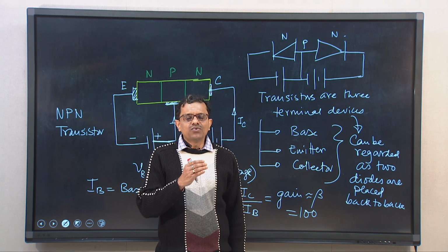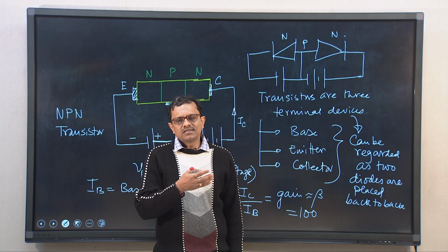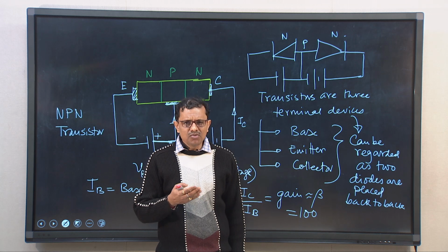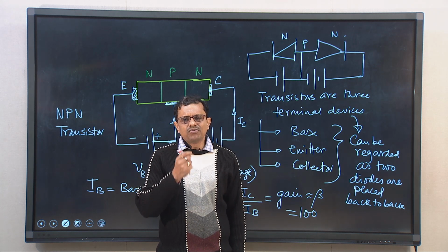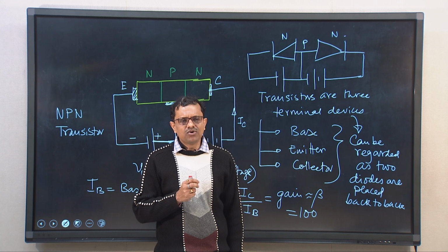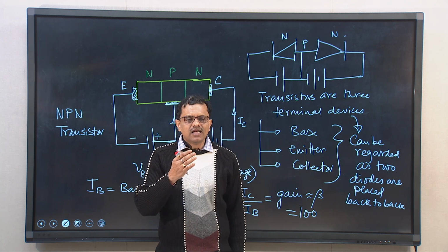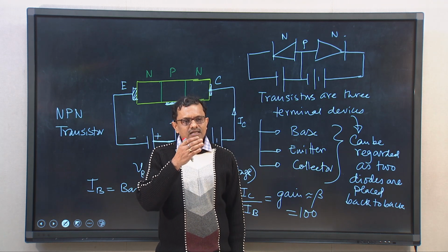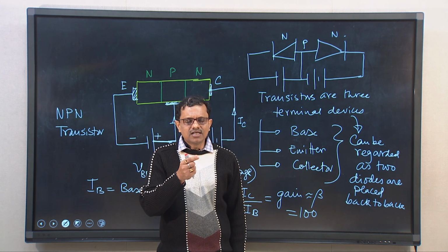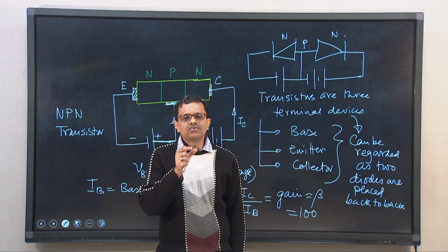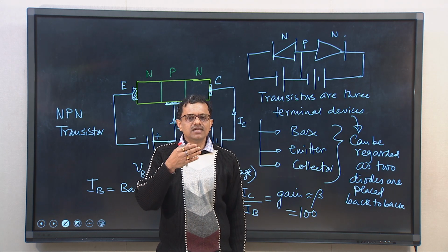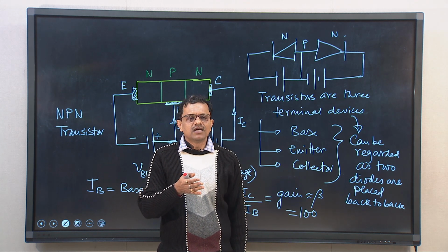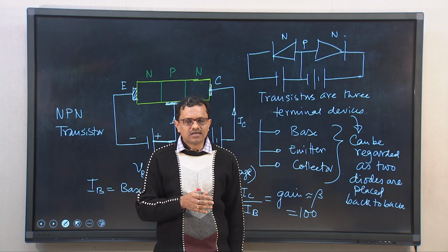The signal received from the sensors is a very small electrical voltage, like 0.05 volt. So, we need to amplify that, and to amplify that signal we need this circuit, so that the ECU or engine management system will receive very clear and proper information about what to do next, what information is to be provided to other systems, so that the engine can always be operated at its optimum condition.